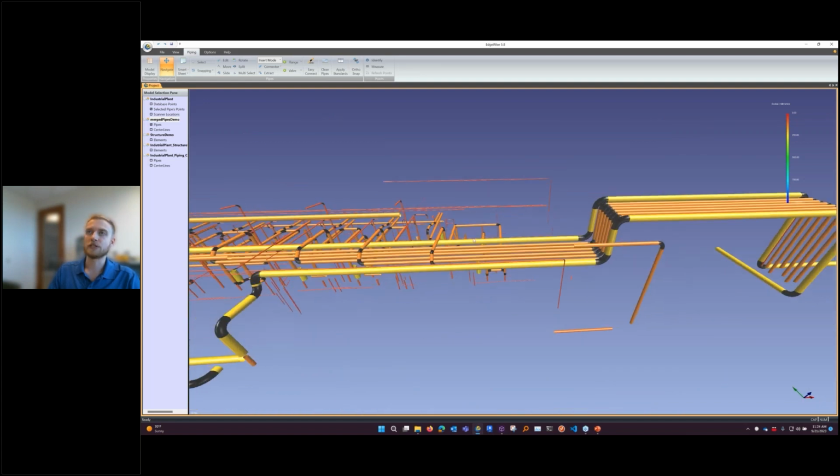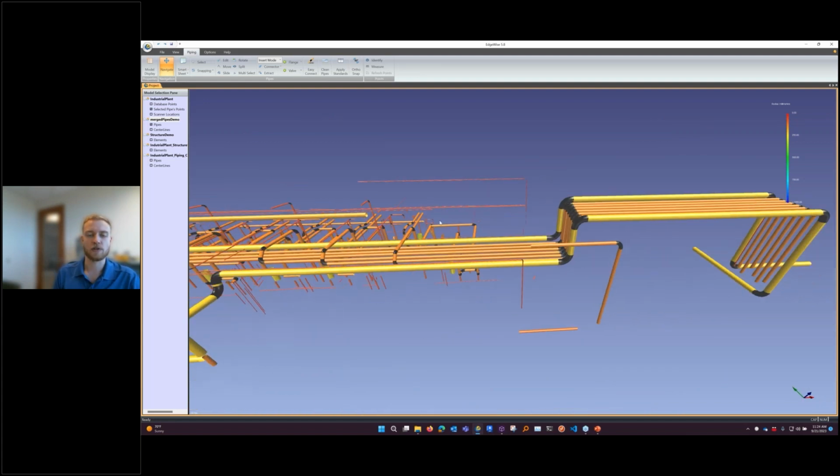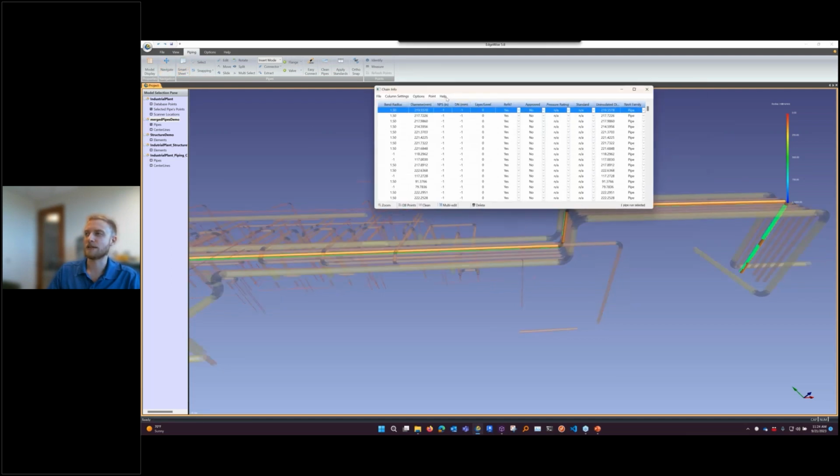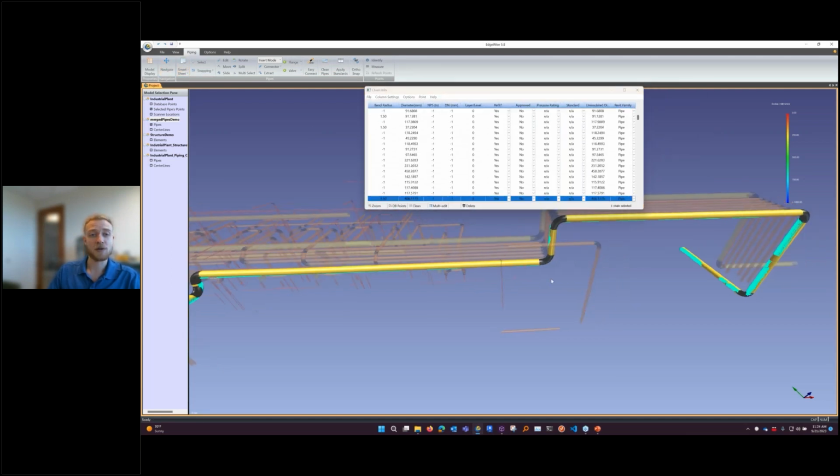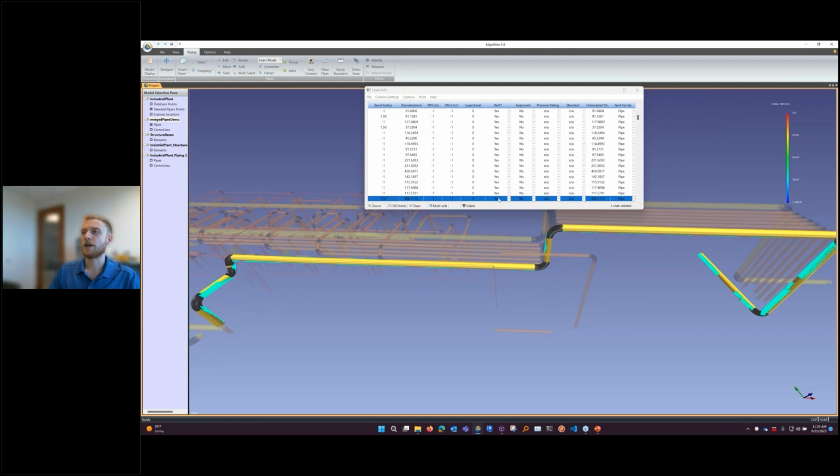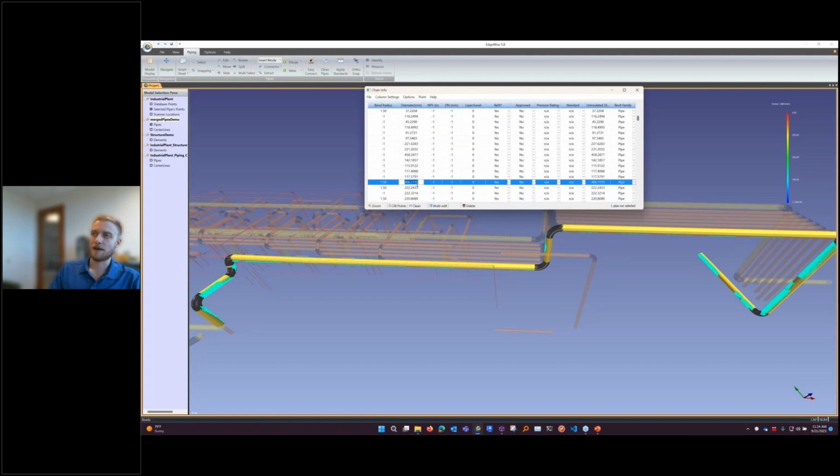The thing we're going to start doing now is what we consider applying our intelligence. What we're looking at is just cylinders. We're looking at runs of piping that are accurate to the point cloud, but are not based on specs yet. So the diameter for this pipe run is just a number based off the point cloud and some averages for the diameter.